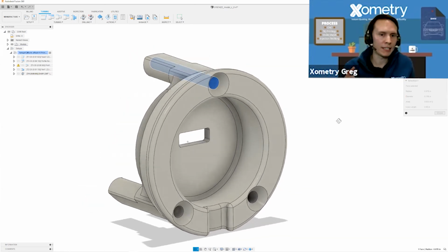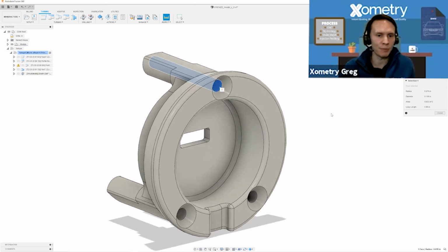And when you do not have dimensions on a part, we don't have a drawing with your part, then we are holding you to those general dimensions and tolerances. You will need to provide what you'd probably consider in your shop an IPI, an in-process inspection, or a final inspection report that you could generate.